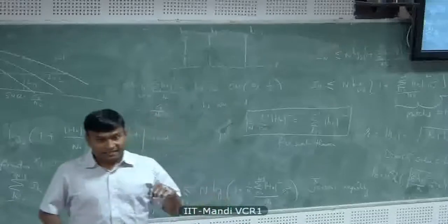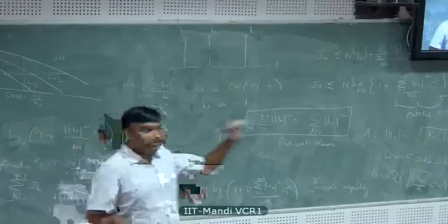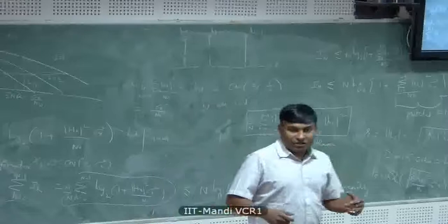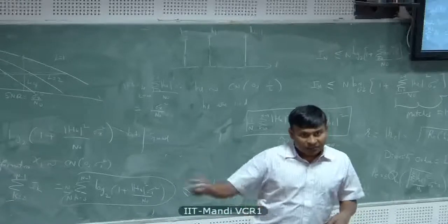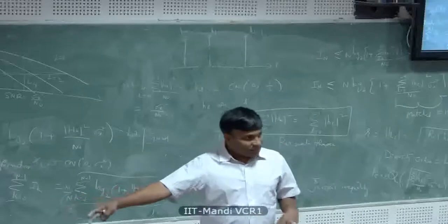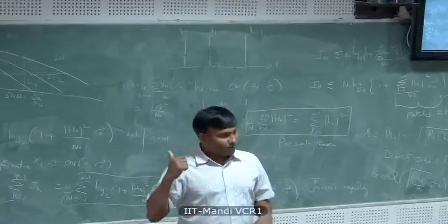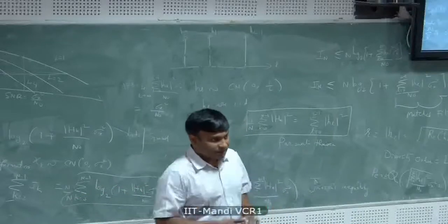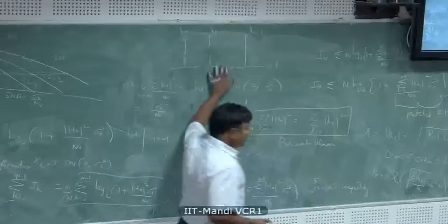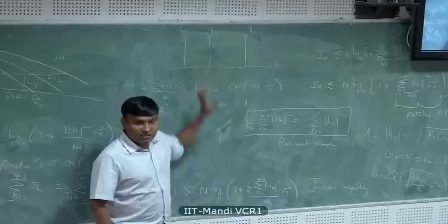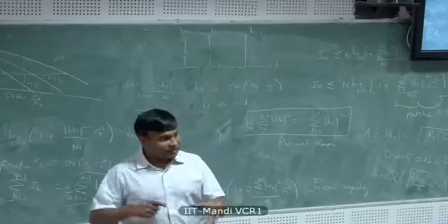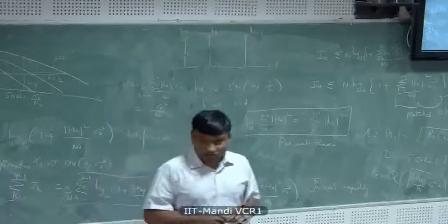But these antennas can be cleverly used for other purposes, what is called spatial multiplexing, MIMO in a more general context, to increase the data rate. That we'll talk about in the next half of the course. You can still use antennas, but for a different purpose. So this kind of diversity we don't have control over. Unfortunately, this kind of diversity you don't have control over because this depends totally on the environment, urban, suburban, rural, and so on and so forth.